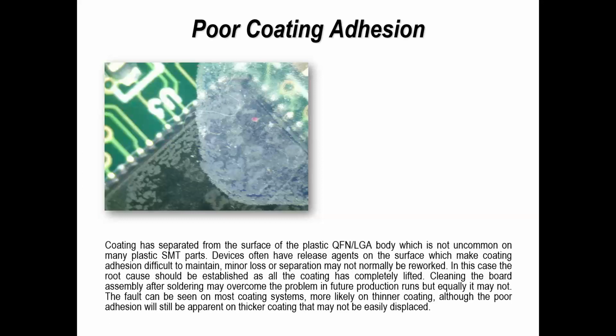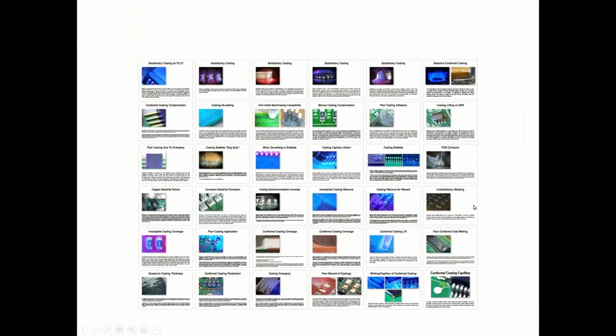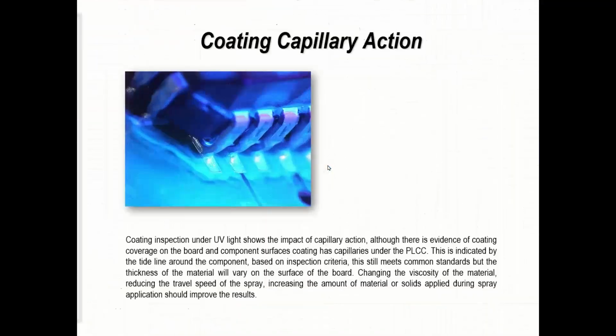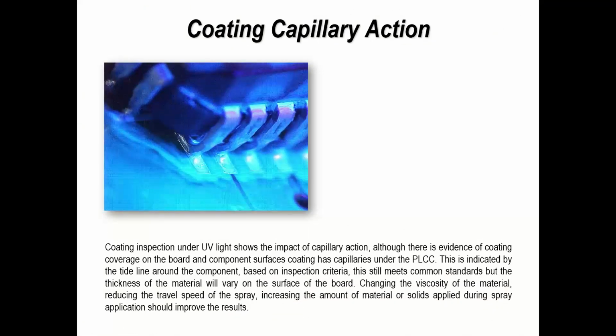So that's one technique. And if you are really serious, this is a real critical problem to you, the cost of doing this is insignificant. If this is a consumer product, the cost is significant. So again, you've got to look at that. But plasma cleaning is available from some companies to do that for you. Or you can rent a unit, loan a unit, just to overcome that particular problem. But again, talk to your coating supplier, but also talk to your coating contractor if that's a particular issue with you.